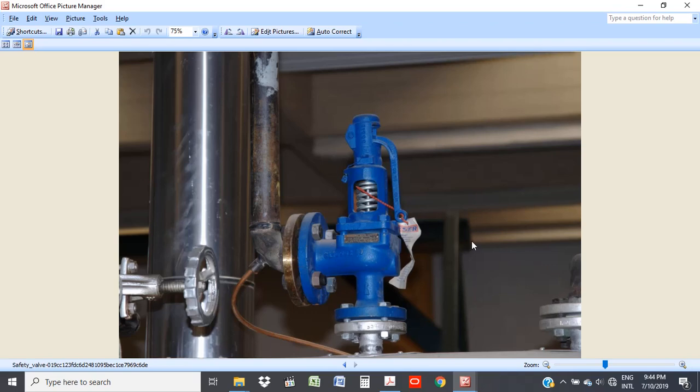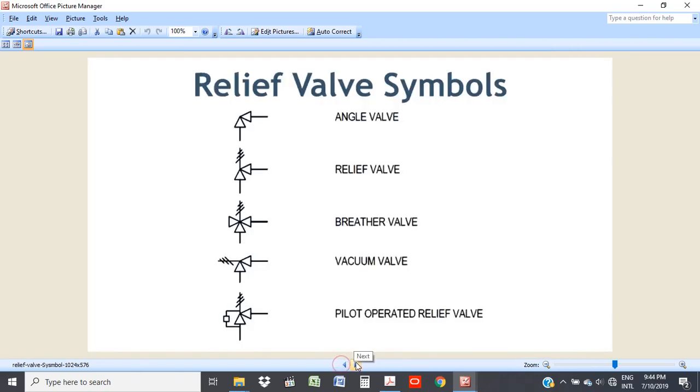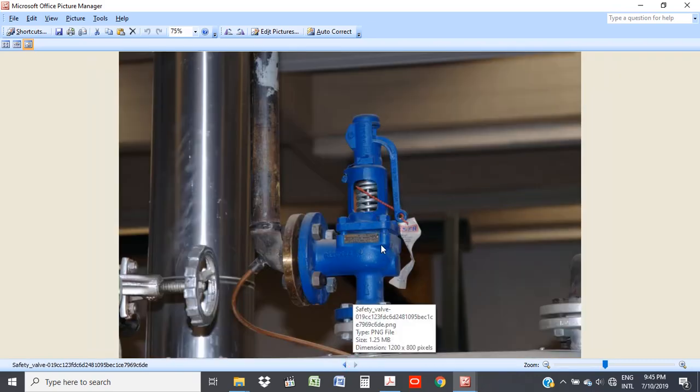So you have a relief valve on top of the vessel that is set to release the extra pressure, the gas in the system, anytime it sees close to 10 bar. Anytime you're getting close to 10 bar, this relief valve pops open and allows the pressure to go to the flare. It's always connected to a flare line, a vent line, and the pressure gets burnt off on the flare stack. This is very necessary. It is a line of protection.